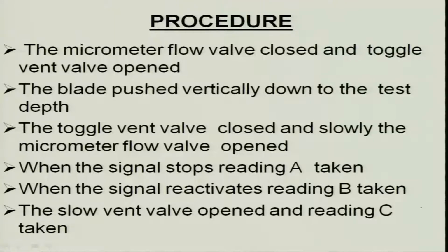So, these are the procedures: you push it inside vertically down to the test depth, then the vent valve will be closed, slowly it will expand laterally and it will give a signal. There are signals outside, you can very easily note it. Also, you can measure outside how much pressure it expands.